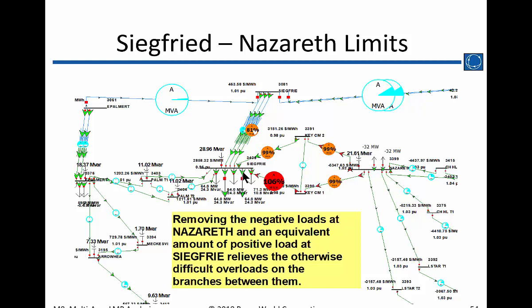And you could take one of the 64s out and then remove two of the negative 32s, and it wouldn't change the net load, but it would very much change the flow that's going across here, because it looks like you have a generator here and some loads here, and most of that's taking the direct path across here and overloading these lines. You could just ignore that line, or you could take these two off and take one of these off. And the net load in the area would be the same, but the flow going directly across would change quite a bit.